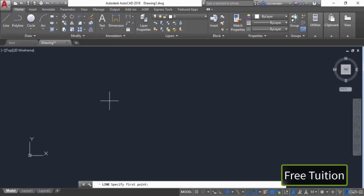Alternatively, you can also use its command equivalent, line, or its command shortcut L, and simply press enter to start the command. So let's type L and press enter, and here also we have the line command. Now after starting a command, you'll notice that the command line will show in bold letters the name of the command or the command equivalent of that command, and also the instructions that you can follow to make the geometry.